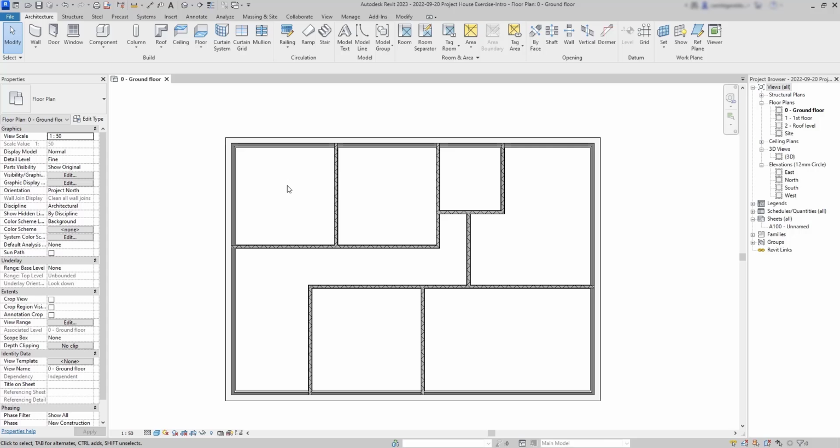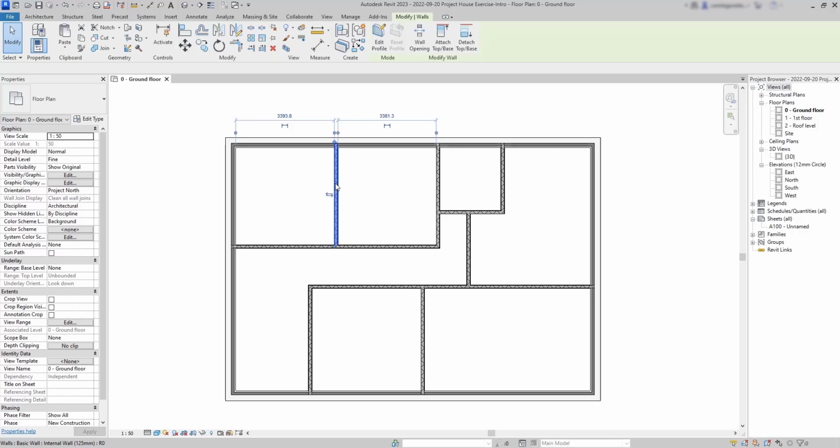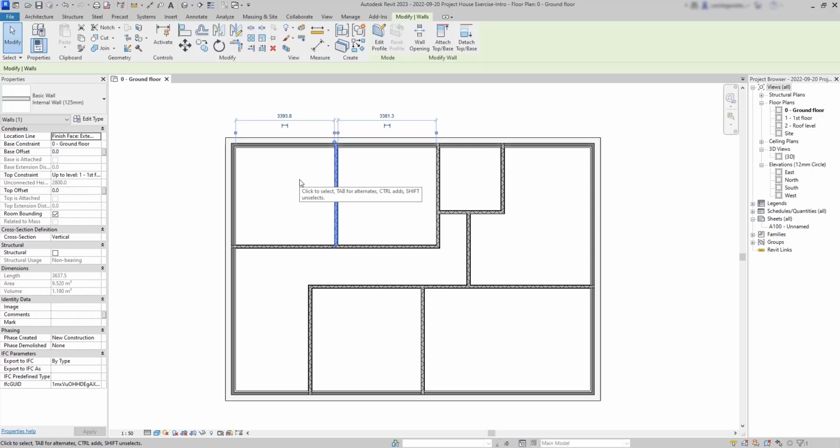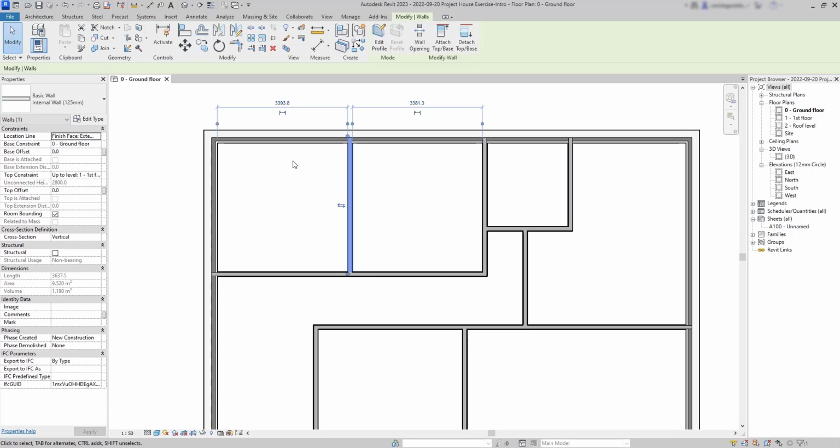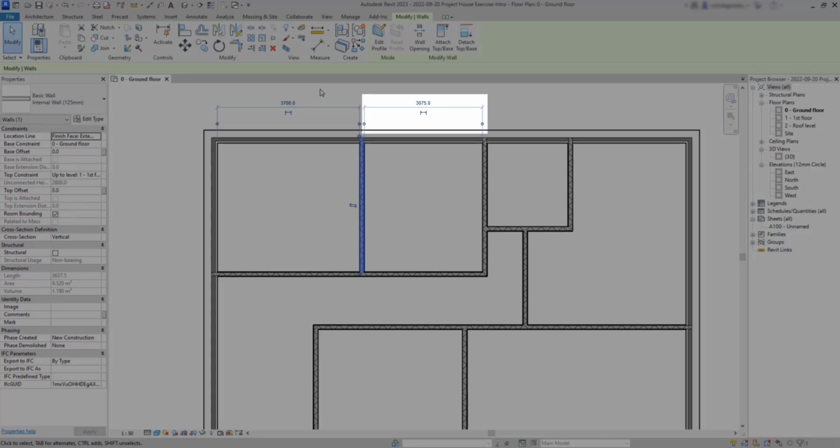Let's start from the top at the left side and select this wall. Now look, when you select a wall, these temporary dimensions show up on the screen. Their purpose is to indicate the distance to the nearest intersections, in case I need to move the wall to the sides. Here, this length has to be 3700 mm, and I simply click on it to edit the value. Just this, easy. Then, the next dimension also changes as the wall moved to the right.